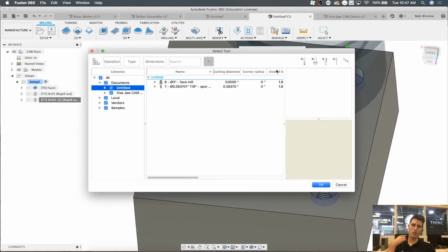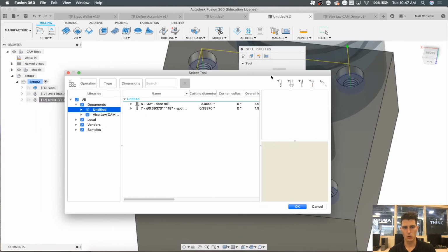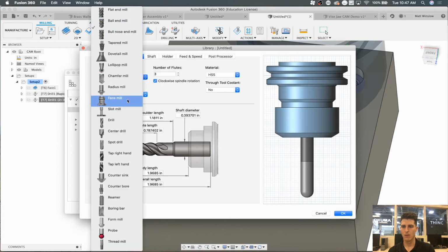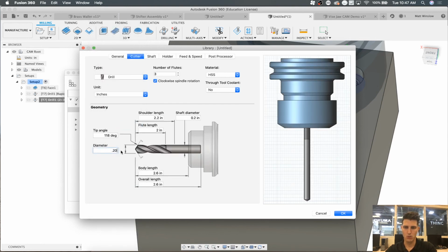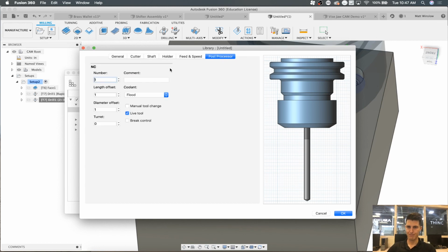Okay, in this case, I believe that was a 1/4-20, so I need a 201 drill. If you didn't know, you could look on your drill chart. So I got my drill, diameter is 0.201, or number 7, that's a 2-fluter. Speeds and feeds, I'm going to drop that down to 100 surface feet. And I'm going to go 4 thou chip load. That'll be tool 8.